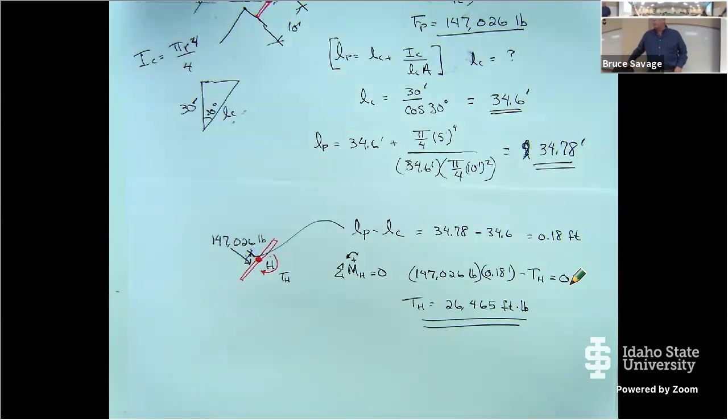If it was simply open and close, we also have to take into account the fluid velocity coming out of the pipeline. And if we're taking this pipeline out of the dam and we have to go vertically down first and then turn an elbow, at those kinds of pressures, we're likely to get really high velocities, which means we're very likely to get cavitation in our pipeline. Cavitation in the pipeline means that we'll start eating away at the dam and there's potential failure. And then the second part of that is that we only looked at one scenario, with the gate fully closed.